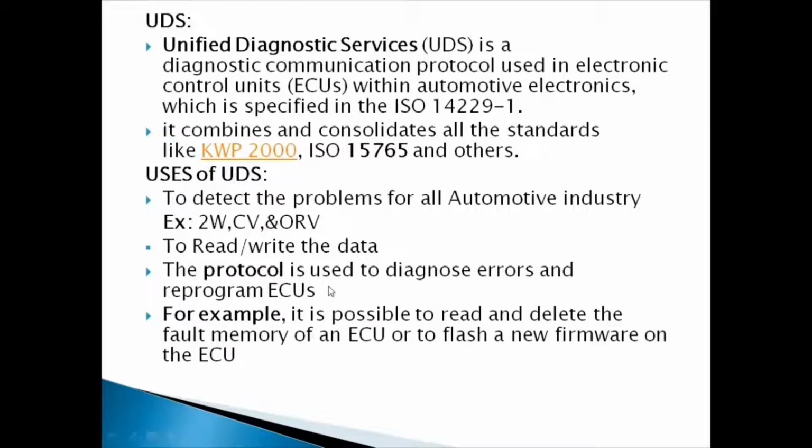It will flash the different SBL and PBL applications. SBL is the secondary bootloader, and PBL is the primary bootloader. We are flashing those files. So for reprogramming of the ECU, we use diagnostics.